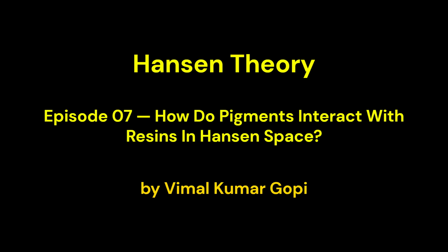Let's start with a common misconception. Many engineers treat pigments as inert. Just grind it in, add it to the resin, let it disperse. This approach works sometimes, but when formulations fail, pigments are often the culprit. Flocculation, floating, settling, color inconsistency, opacity problems, all trace back to molecular interactions.